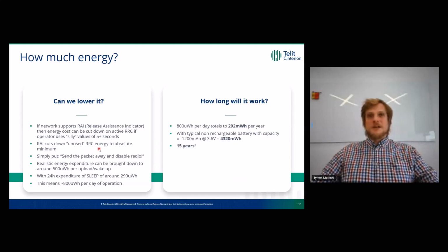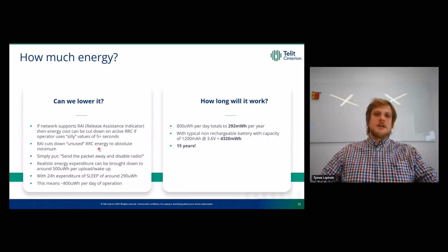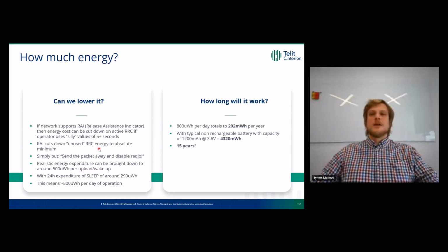So when we are done sending and we are not expecting any data to come back to us, we just use the release assistance indicator, tell the network we are done, and the network goes, yeah, okay, you're free. So simply put, send the packet away and disable the radio. The realistic energy expenditure can be brought down to around 500 microwatt hours per upload wake-up. That also varies between selected modem variants.